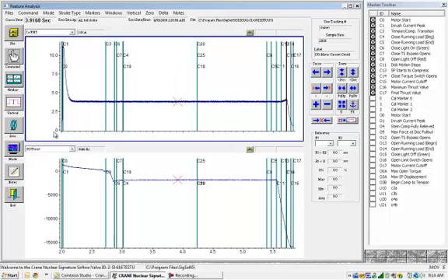Alright, so we developed the motor energized, got the peak inrush faded away, and the stem and spring pack are moving the other way on the worm. You get to your zero plateau in here. This would be your closed running load. You'll have hard seat contact, and as your force develops into the seat, your motor current will start increasing until you get to closed torque switch.